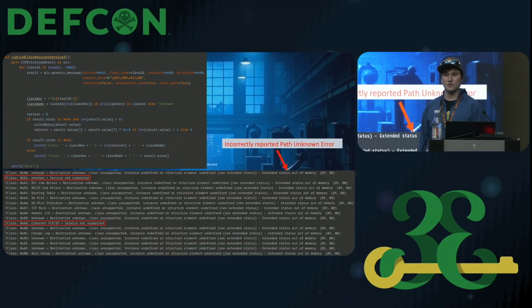It's the object that stores the device's IP address, MAC address, and diagnostics counters for its Ethernet ports. And we got a service not supported from it as well. Well, that's easy. I'm just going to go get the spec out and say, hey, what services does this object actually have in it as part of the specification? Because I know this device now has that object.